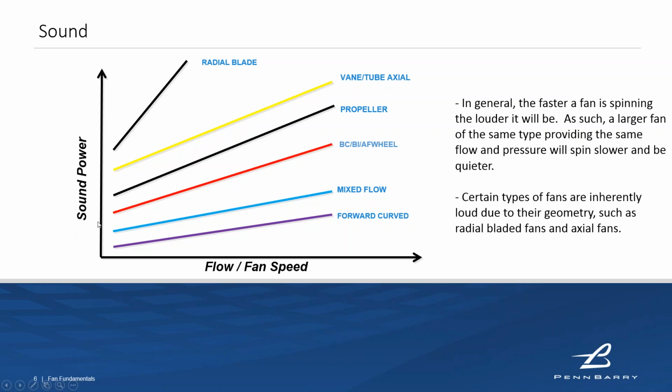In the same way that it's difficult to compare efficiency directly between models and sizes and everything, sound is also difficult, but we can make some general statements about it. One of the first things that's worth pointing out is that the faster you run a given fan, the louder it's going to be. There's no way around that. What the pressure is and what the flow is really are quite negligible. It all comes down to fan speed.